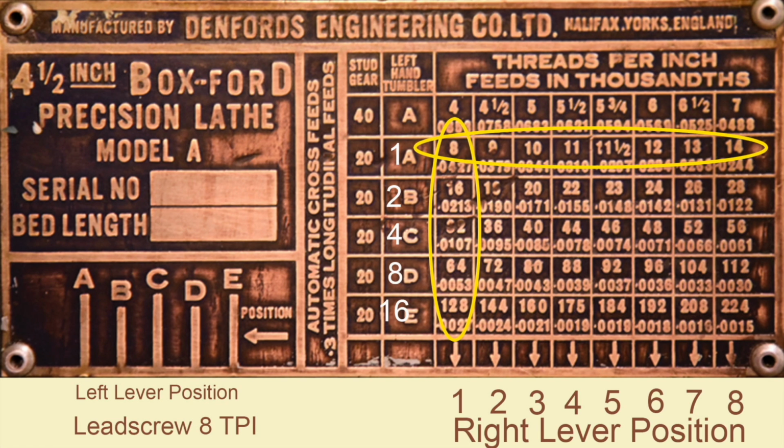To reproduce this whole table with numbers that give the relative gear ratios of all the different locations, we could just multiply the rows by columns. For example, we could take this row here with 64, multiply it by its column 10, and you end up with 640 in this location, and all the numbers would be correct relative to each other, but you've lost the actual value of the threads per inch.